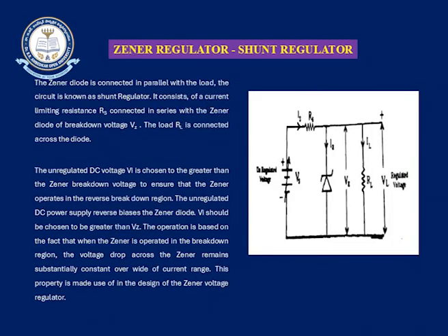That we already studied in the previous section, but here in regulation, the Zener diode, you can see from the circuit diagram, has a variable source. Vs is the variable source, and the arrow mark indicates that you can vary or change it. Here the source resistance is Rs. Whenever V and R are there, definitely a current Is is going to be generated according to Ohm's law.